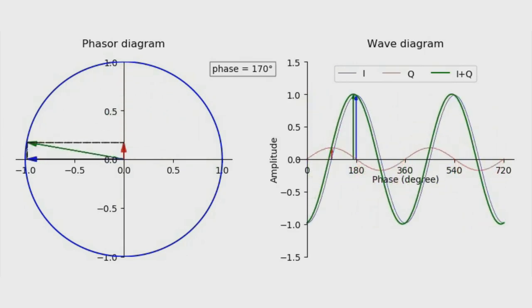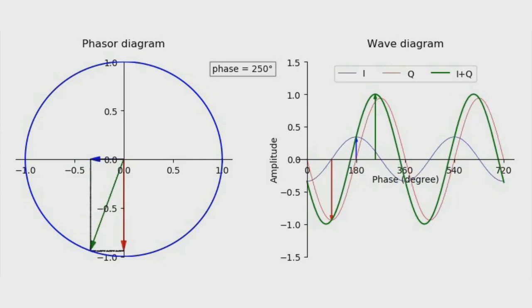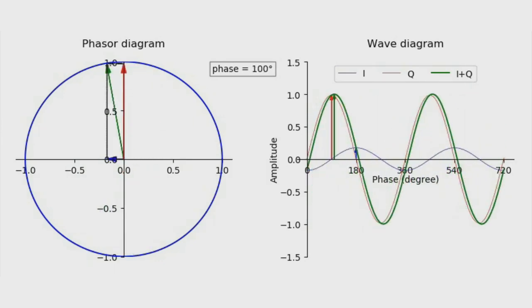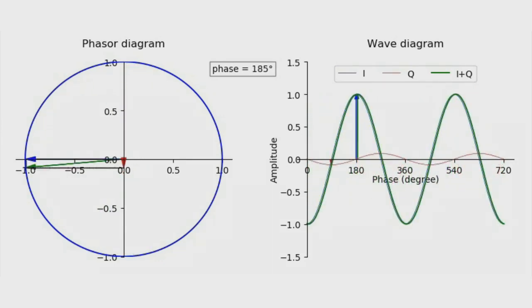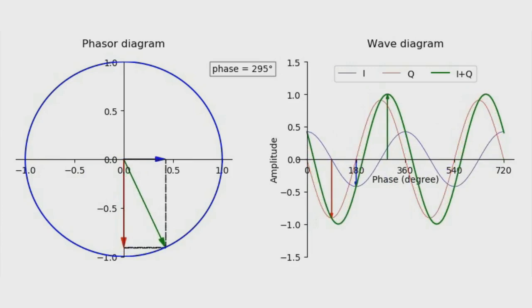So there we got some IQ or quadrature modulation going on. The phasor diagram, or the phase between the two signals, is shifting as those two waveforms change phase from each other. Any signal you've got, if you break it down with I and Q, it's going to show up somewhere on that phasor diagram. You've got an amplitude and you've got a phase, and you just pick out the point along there and you can recreate any waveform you want.